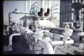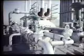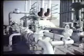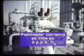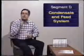De-aerators have been used for many years and have been developed to be highly reliable. We expect the feed water coming from the de-aerator to contain as little as 2 parts per billion of oxygen. But why do we go to all this effort to expel oxygen and other gases which may be dissolved in the condensate? Well, it's for protection of the boiler internals. The presence of even very small quantities of oxygen in feed water can lead to severe corrosion of the boiler tubes. This factor is so important that chemical means are also adopted to keep oxygen out of feed water. And we'll be talking about this in a moment.